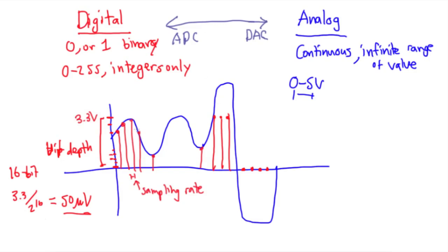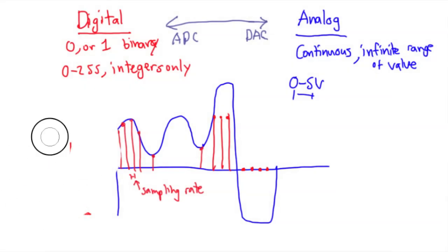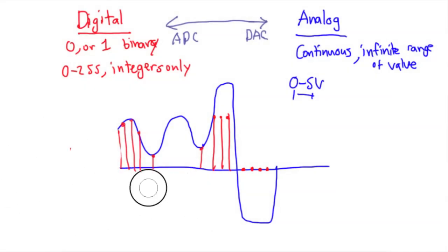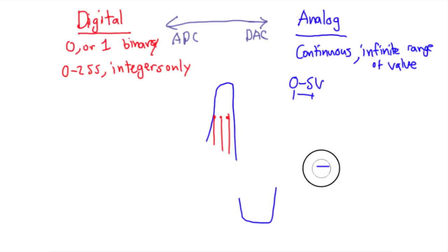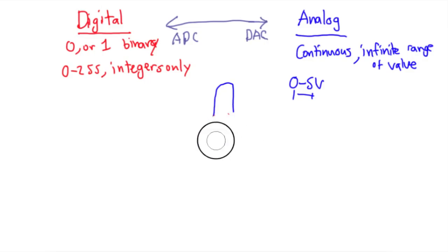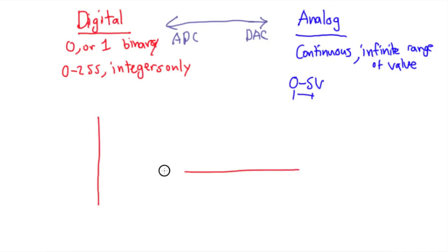So it's going to be trying to make this blue wave right here. I'm going to go ahead and just start over here. Actually, we might want to erase this and restart. So the idea behind this, again, is there's going to be something like the inverse of a sampling rate. This is the time it takes for the microcontroller to change voltages constantly over a set period of time. We're going to draw a red graph to indicate the digital signal, and then a hypothetical blue signal that the digital to analog converter is going to try to become. So something that looks like this.